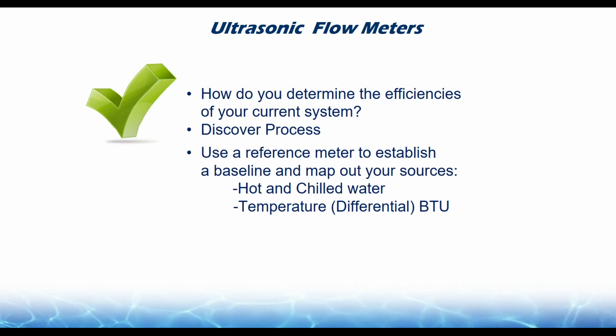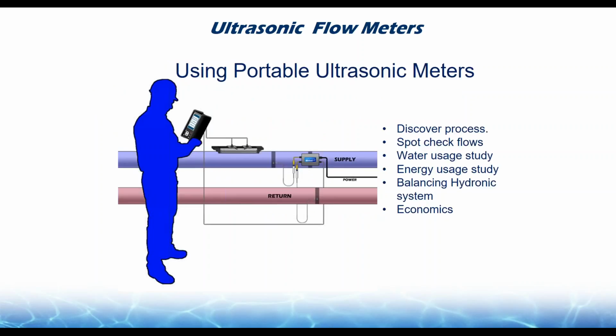We've got to monitor the hot and the cold water and look at temperature differential, calculate energy use. All these different sources there, you can put metering in line to monitor this, but it's not practical sometimes to put 100 different meters throughout a facility. It's not economically feasible. So we need to have tools to go through a discovery process to, one, get a hint of what we have, and then two, if it's outside that box of what's practical and not practical, then we need to put dedicated metering there to control those applications or enforce their limits there.